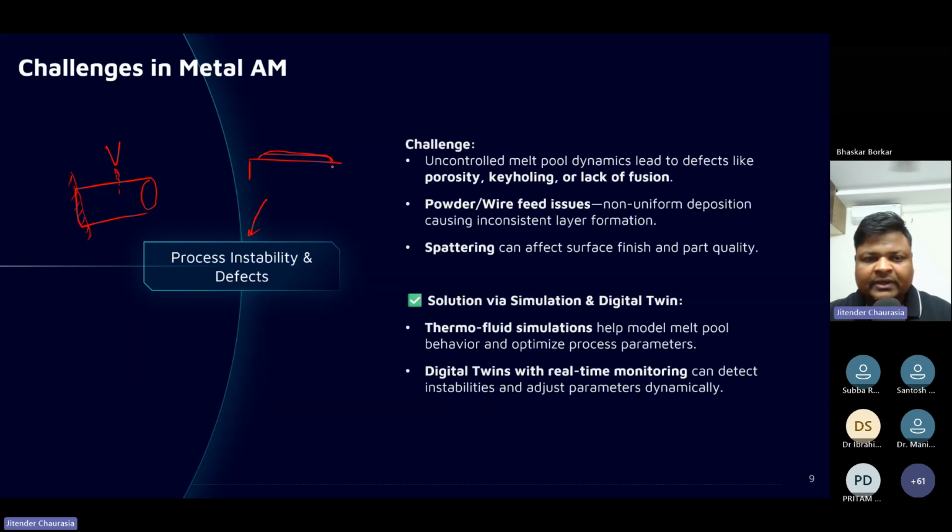So you have your base at a certain temperature and you quickly deposit layers and you're done. Just do some sort of machining with the GD&T of the part. But when it comes to DED, we are building the part. So you have a substrate at the bottom and you are depositing almost like 100,000 layers. Now here you have only thermal histories. You have a layer at this temperature and a layer at this temperature, and you're done.